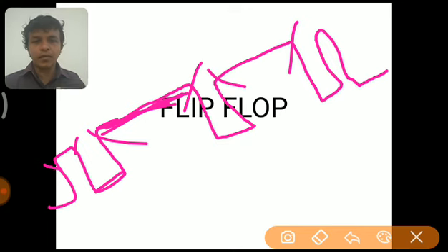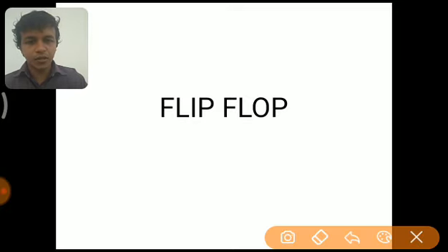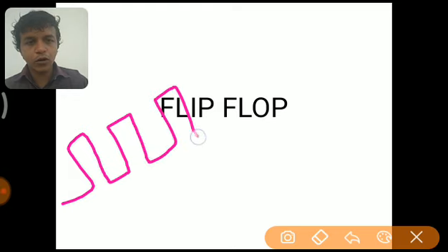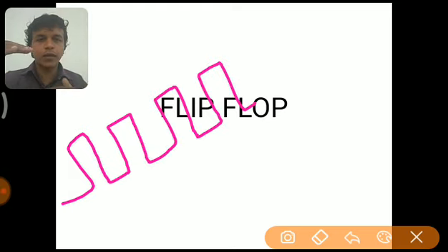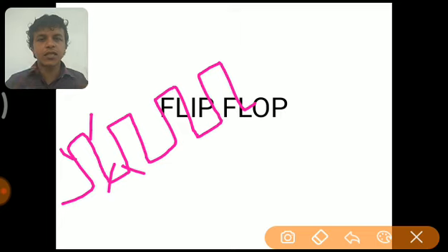It is not easily controllable, it produces output whenever the enable signal is high, and it is level triggered. So this makes the latch not usable in circuits the way flip-flops are. Whereas flip-flop is not level triggered. Flip-flop is edge triggered, and we are not giving any enable signal as the controlling unit. Instead of an enable signal, we are giving a clock pulse, and the higher value and the lower value of the clock pulse are maintained for a fixed time interval. The duration between this point and this point is also fixed. So it maintains a constant time interval throughout.